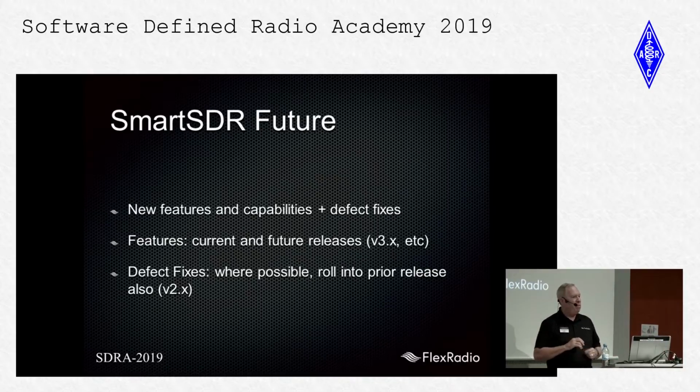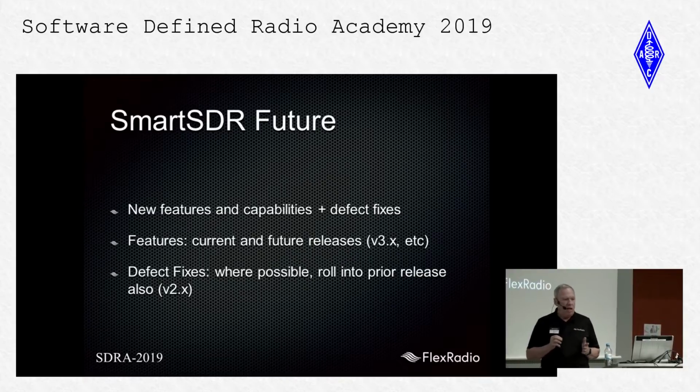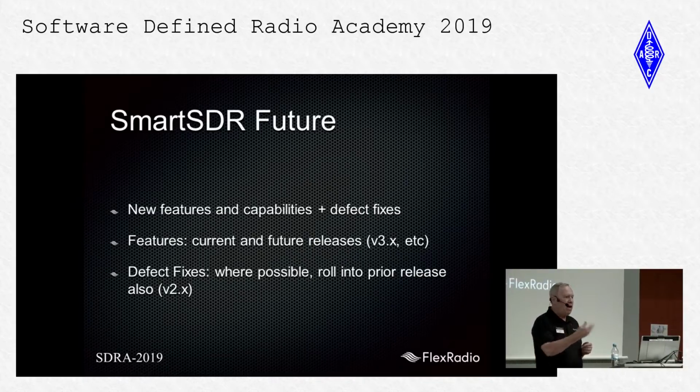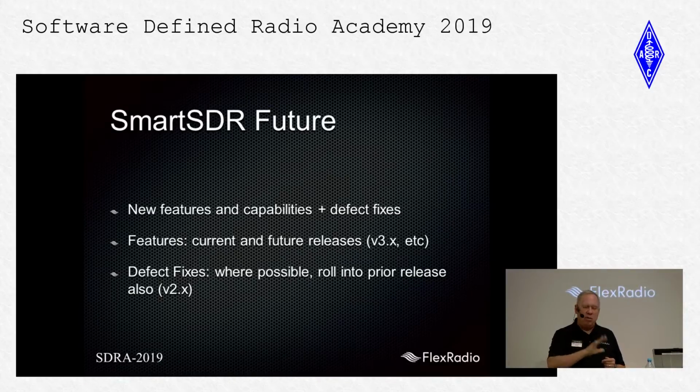Is anyone here familiar with the concept of ALE? I've just lost the acronym. Anybody remember the acronym for ALE? Let me describe it. ALE means the ability to contact an individual user on the best band for your propagation and on the best frequency where you can both talk to each other.